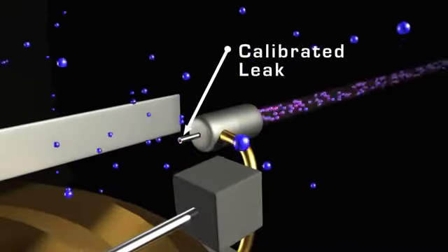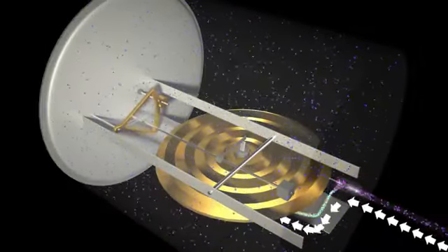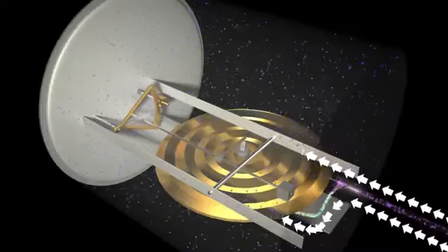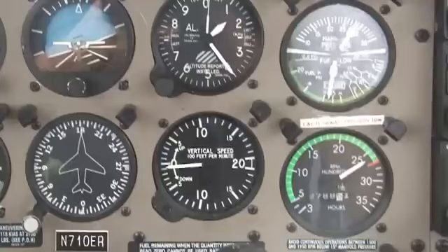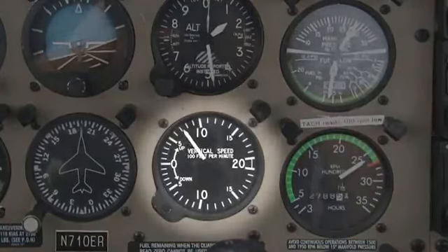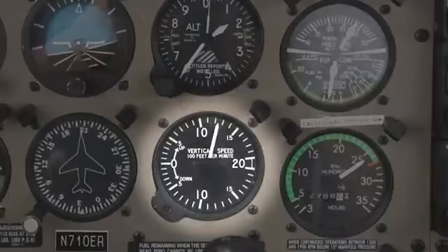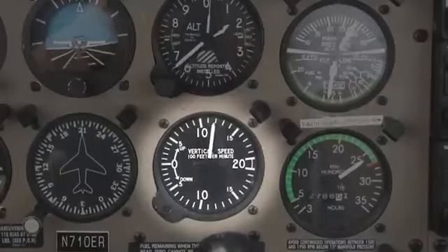case can change. When a plane climbs or descends, the diaphragm pressure will change instantly, but the case pressure changes slowly. This results in two different pressures. The difference in pressure allows the instrument to display the vertical speed. Be aware, however, that it takes a few seconds to read accurately, so anticipate a slight amount of lag. Here's an example of how it works.